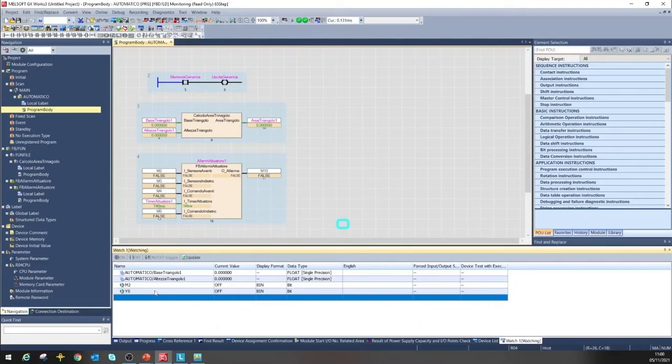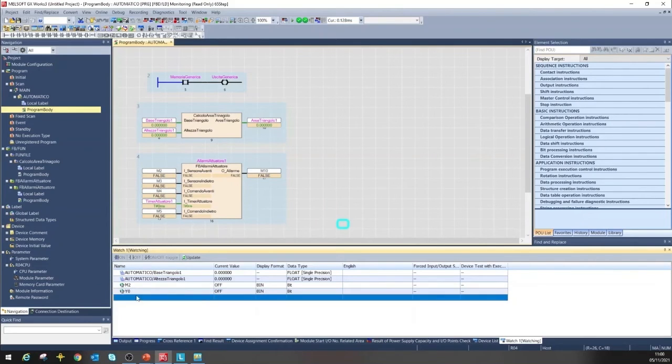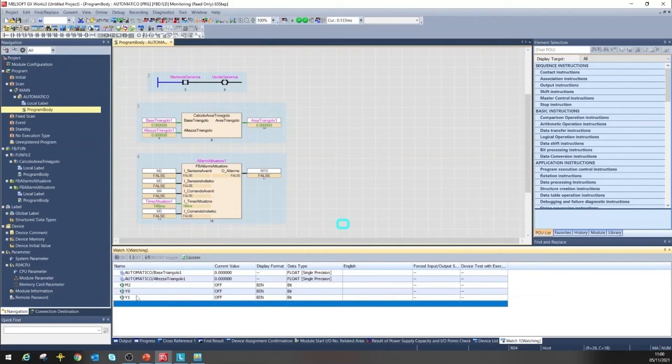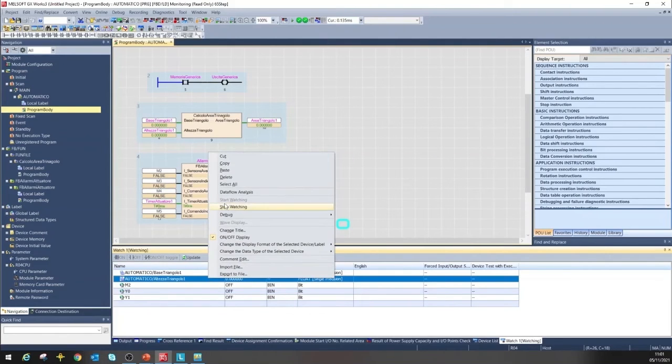We are talking about verifying that they are electrically connected correctly, ensuring that our outputs brought to an active logical state by the software actually drive the load. So the little trick can be to put the PLC in stop and then work on, in this case, Y0, Y1 on our output devices in stop. So we will then go and change the state of these variables.